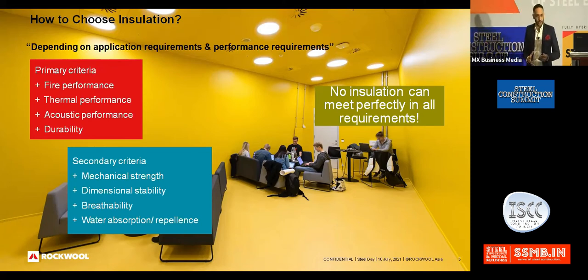Now, to summarize the point, stone wool, the material that we are manufacturing, is the only material which will satisfy all the primary criteria. That includes fire, because the melting point of our material is more than 1150 degrees Celsius, which is actually more than a 2-hour fire temperature. The fire after like 10 minutes reaches 600 degrees Celsius. After 1 hour, it reaches around 925 degrees Celsius. And after 2 hours, it reaches around 1049 degrees Celsius. So our material is absolutely fire safe even after 2 hours of fire, because the melting point is more than 1100 degrees Celsius.